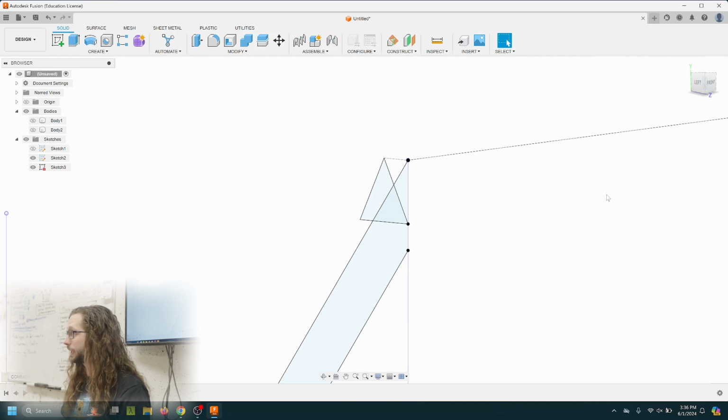You can constrain non-construction lines using construction forms. In fact, that's the whole reason that construction lines exist. It's just that they're not going to get included in whatever transform you're doing. So notice I have a closed form with this triangle, but the closed form between my construction line and the edge of this isn't, because the construction line doesn't get to make closed forms. It's not something that you get to use in a transform. It's just there to help us line up this point with this point.